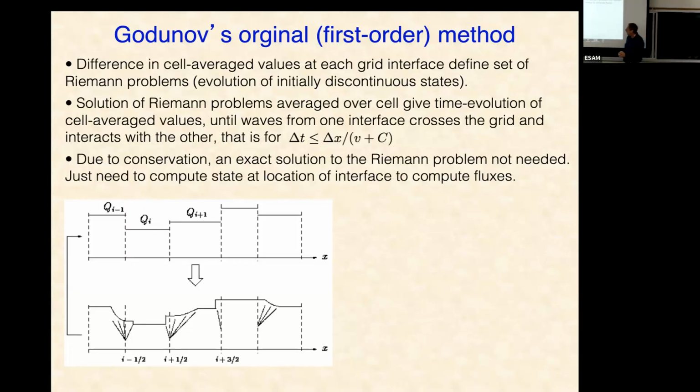The Riemann problem can be solved analytically and would result in, for example, in this interface, you might drive a rarefaction wave to the left and a shock wave to the right, in opposite directions for these other interfaces and so on. Each interface would behave according to the jumps in all the conserved variables, which you can compute analytically. And then at some later time, all you need to do is integrate these curves over the volume of the cell, and that gives you your new volume averaged value at the new advanced time. You can do this until the waves begin to interact. When the shock wave launched here interacts with the shock wave launched there, then that's not an analytic problem anymore, because now the shock waves are interacting with each other. So you immediately get a CFL condition built into your method. You can only evolve it for a time which is less than the wave crossing time of the cell.